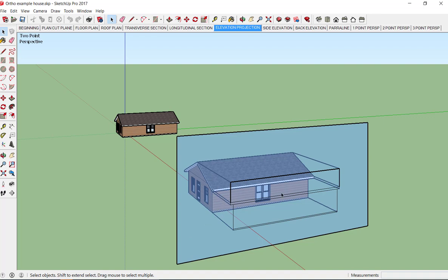I'm taking that elevation, I'm square to it, and I'm just drawing the lines out straight, perpendicular to the building. And where they hit that piece of glass, for example, that line's coming from the ridge of the roof, this line's coming from the top of the fascia, this line's coming from the bottom of the fascia. And obviously there's a line that connects up from there to there, and I can draw that up.